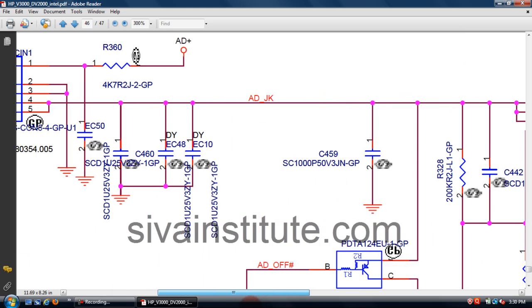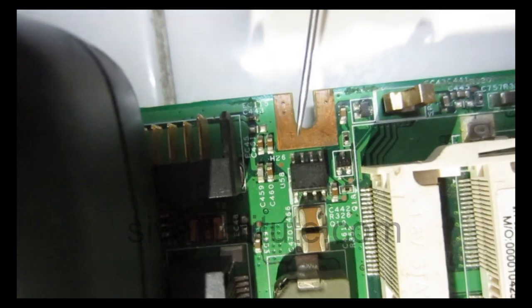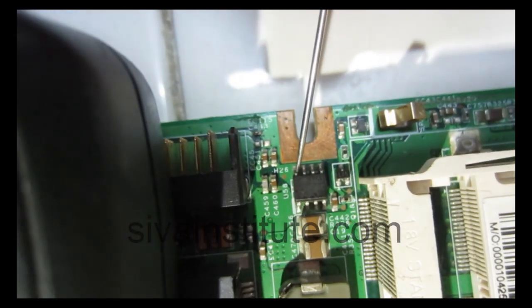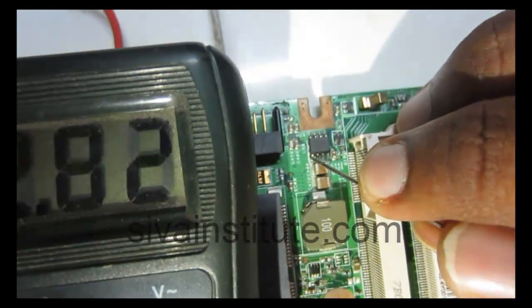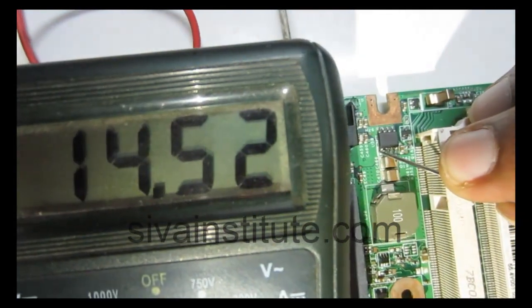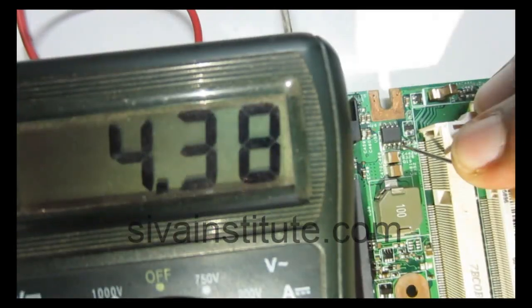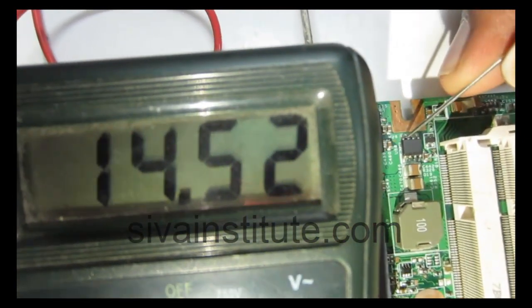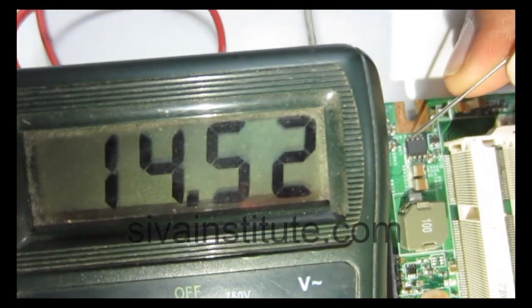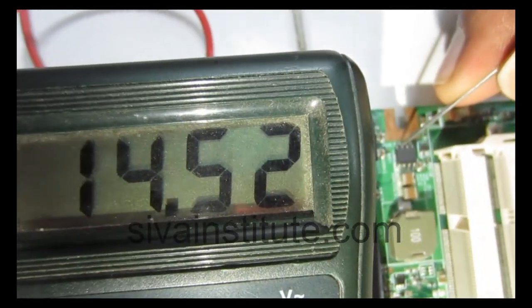I will short this transistor here and we will see. This is U58. This is the input voltage, pins 1 to 3, 14 volts input. Gate pin number 4 is 4.5 volts. Output 14 volts. This is okay. When there is no voltage at this point, you should check Q18 and Q19.